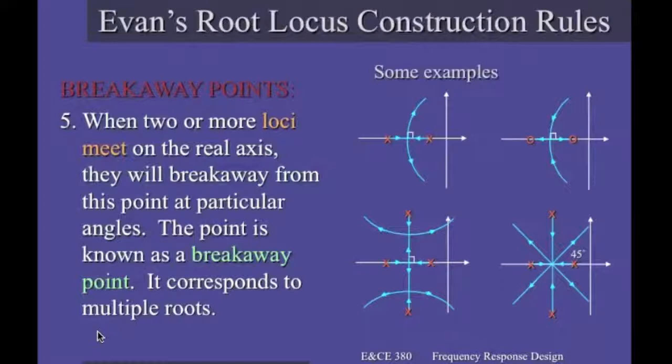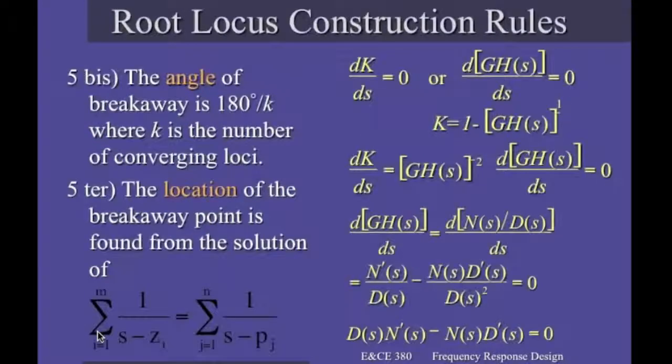The reason is that this depends on the open loop transfer function, so on the numbers, on the coefficients that are inside it. Because you may understand this, even though the degree of the equation stays the same, you may have different equations when changing the numerical values for zeros and poles.